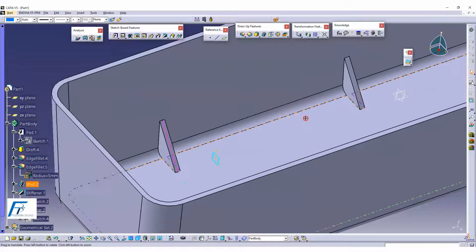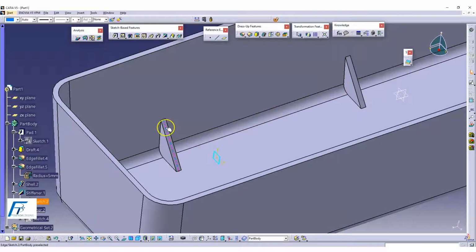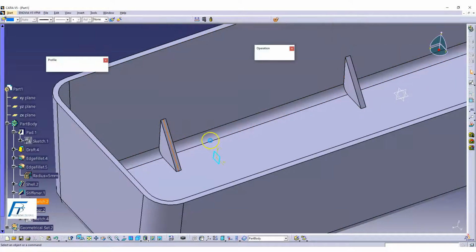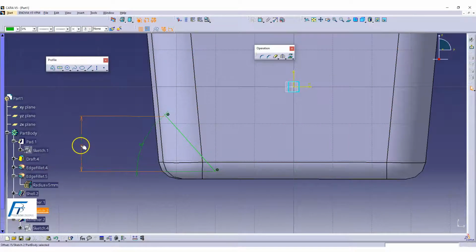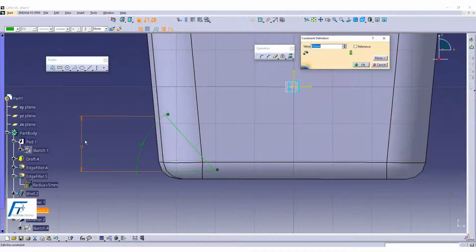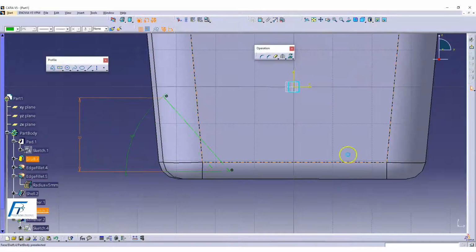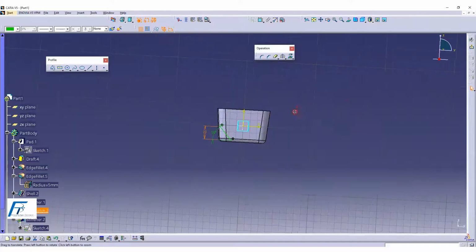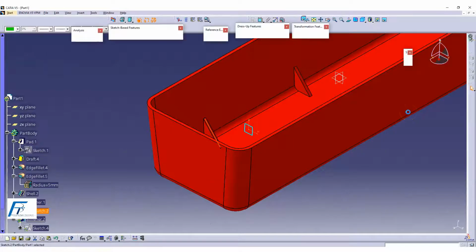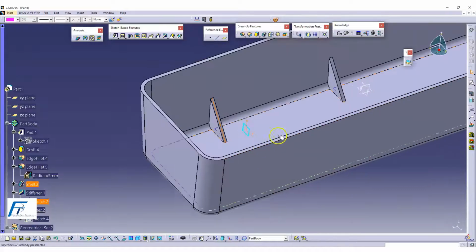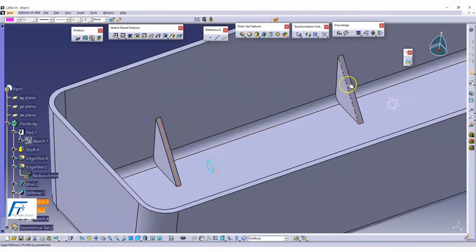Now the moment you make any changes on this sketch, which we did, right? The sketch. If you make a change, say for example I would like to change this one to 15 to 20 mm height, the moment I change it, this also gets changed. See this, because I projected that one. So the moment it gets updated, because this sketch is projected.